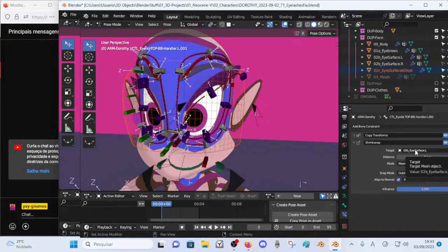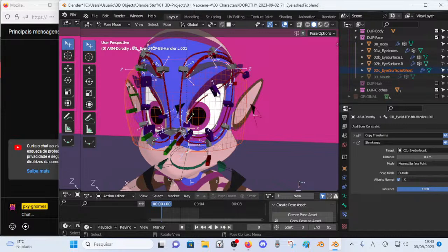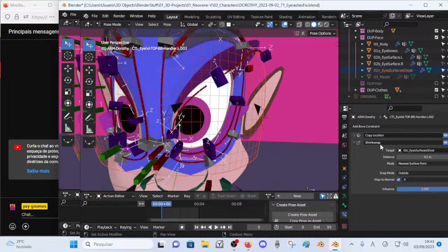If there is a different object target for the shrink wrap bone constraint for the bones on the same armature object, like in this case, I was using this bone and these bones, and they were targeted at different mesh objects with shrink wrap bone constraints, the respective ones start going crazy. And the same thing is happening here, because you see here there are different targets, but we'll move them all to the same target this time.